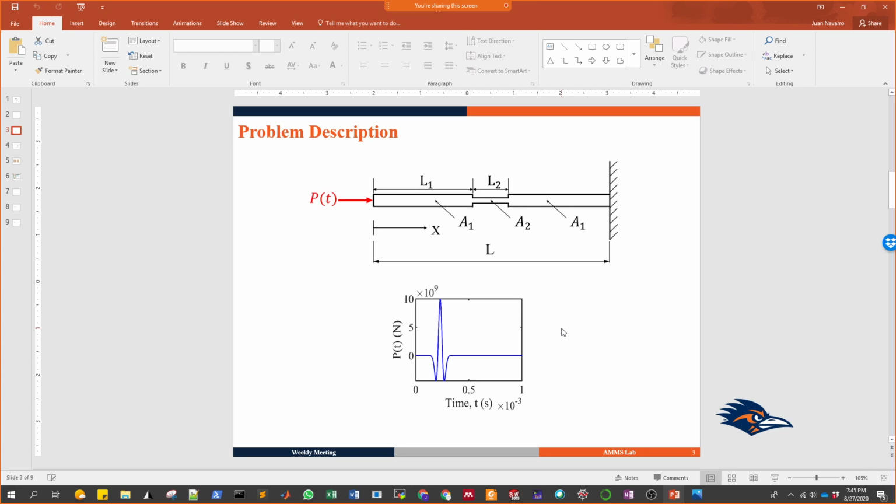With this, we want to find and identify imperfections in a domain. Basically, this is used for structural health monitoring. As you can see here is an example of a time signal of the force. And then what I do is I just go to MATLAB, I create a vector or an array of time and amplitude, and then I just copy that table in ABAQUS, and that's it. That's how I have my boundary condition as a function of time.